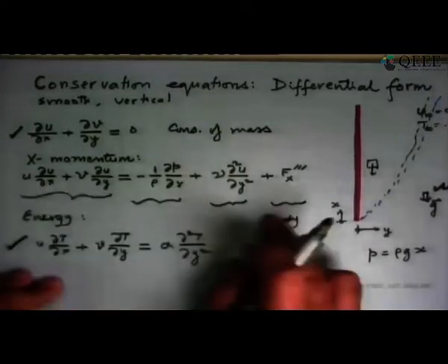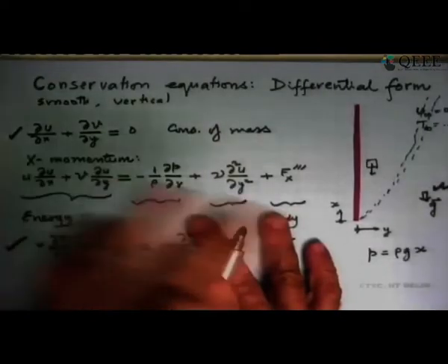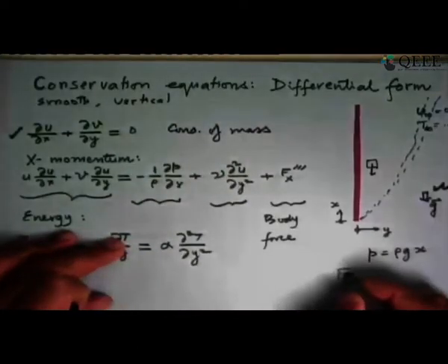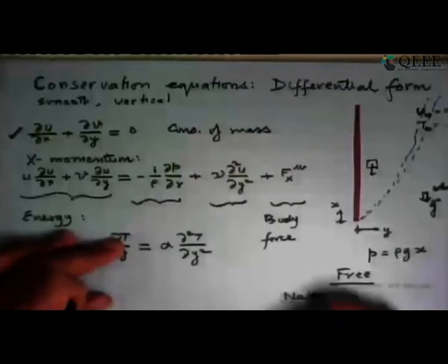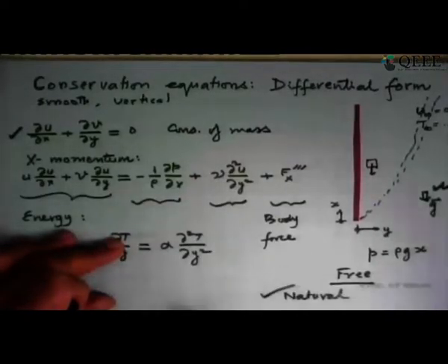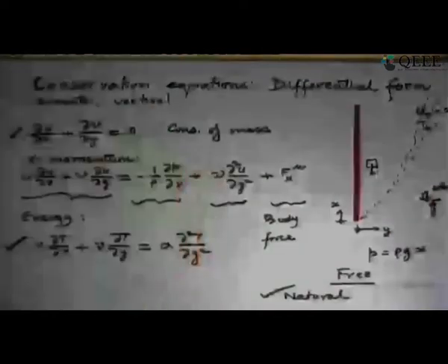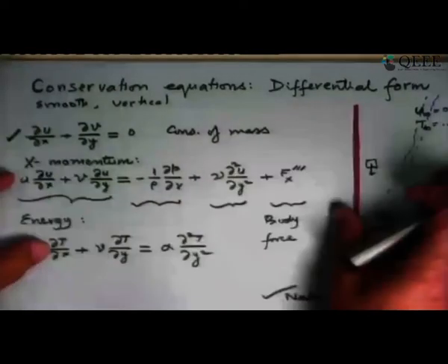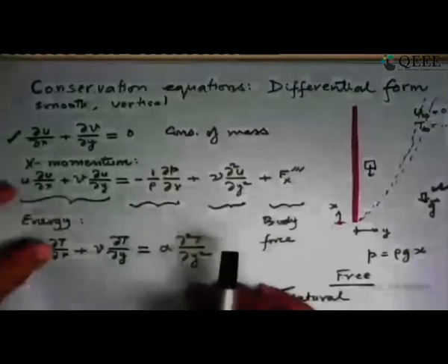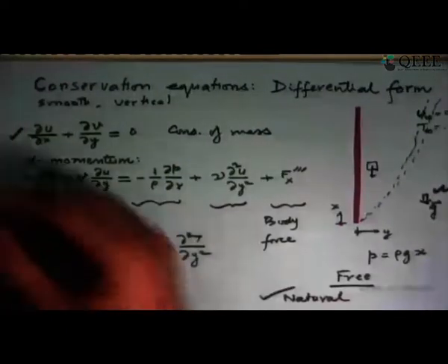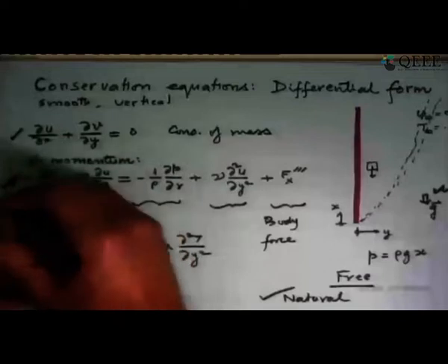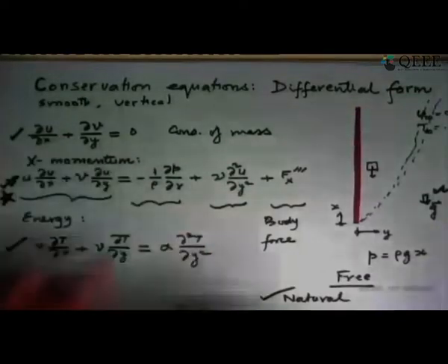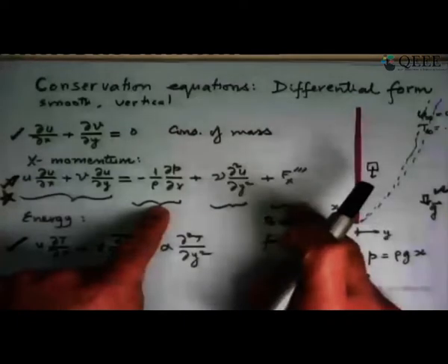So this is the equation that has come up, and this is a fairly general equation. It is not just what we are looking at here. This is actually a case of free convection, but this equation is equally true in general for all types of natural convection. We did not make any assumption at this point at all. If it was a rotating system, the body force would come about because of the solid body rotation induced by the rotation of the fluid. So that is the change, and this is where we have an important difference coming up: you have to now include the pressure term and the body force term, and now see what happens.